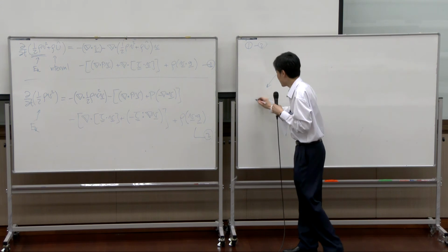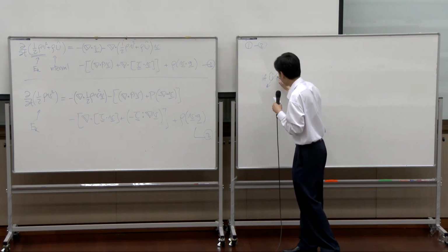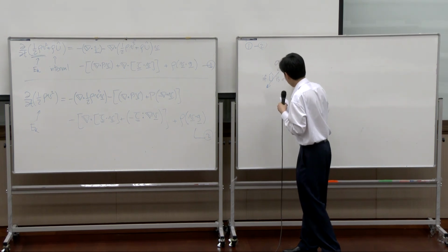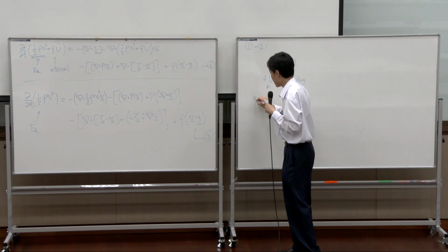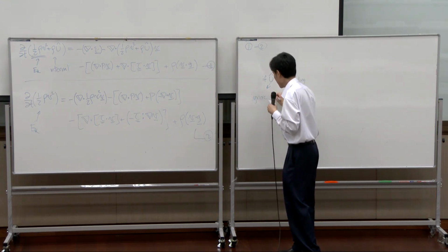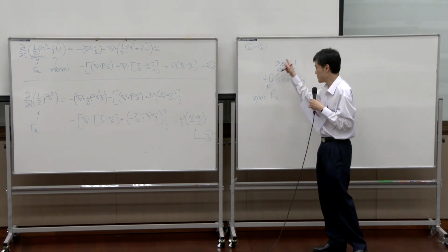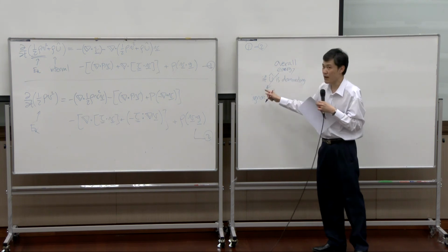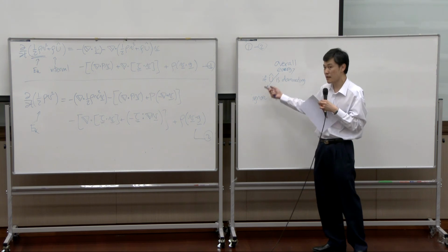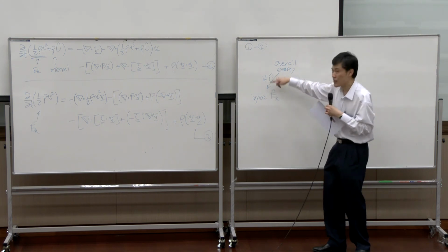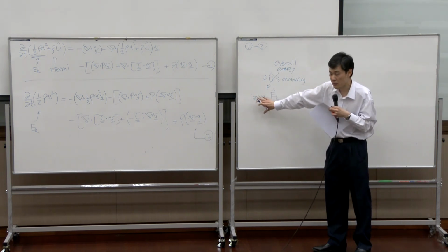So in that case, if U is dominating, you can ignore kinetic energy. Okay, this route here is usually the common route that you took in thermodynamics. Whenever you have system changing in temperature, internal energy change is dominating over kinetic energy change. You can ignore this part. You can ignore kinetic energy part.